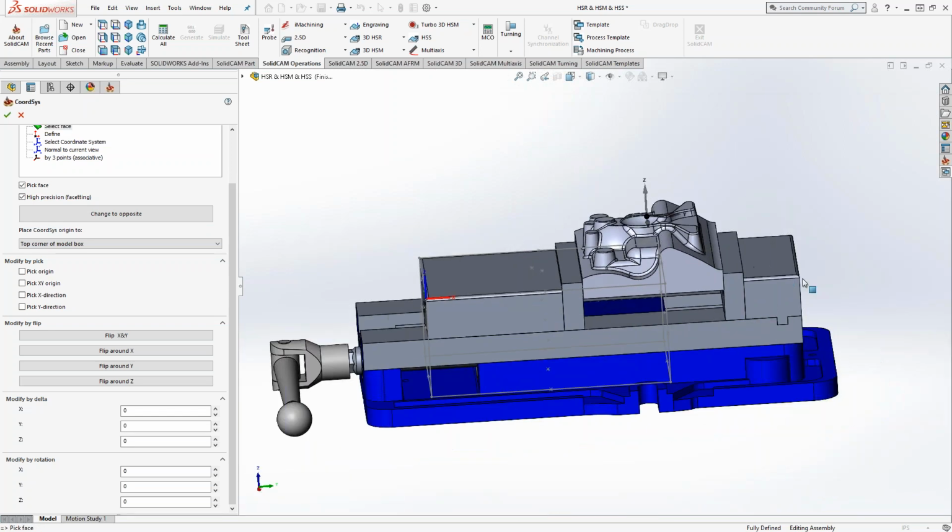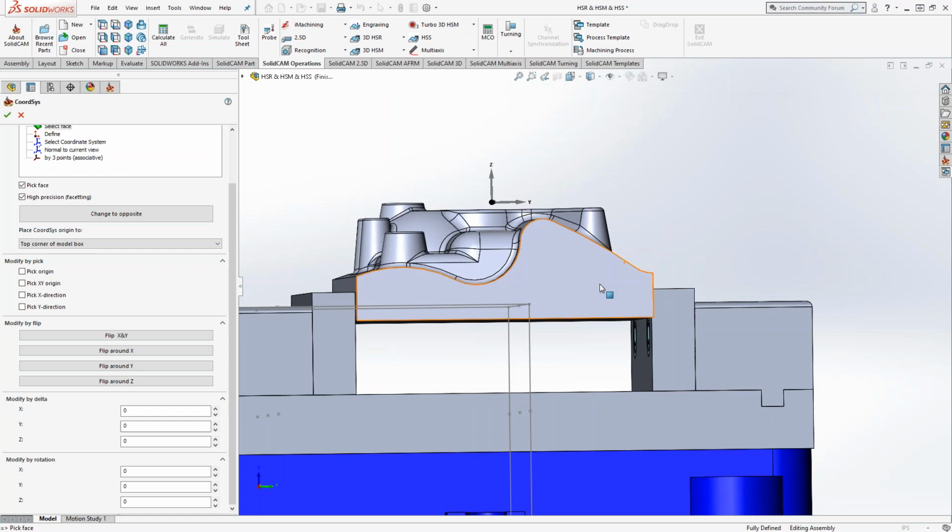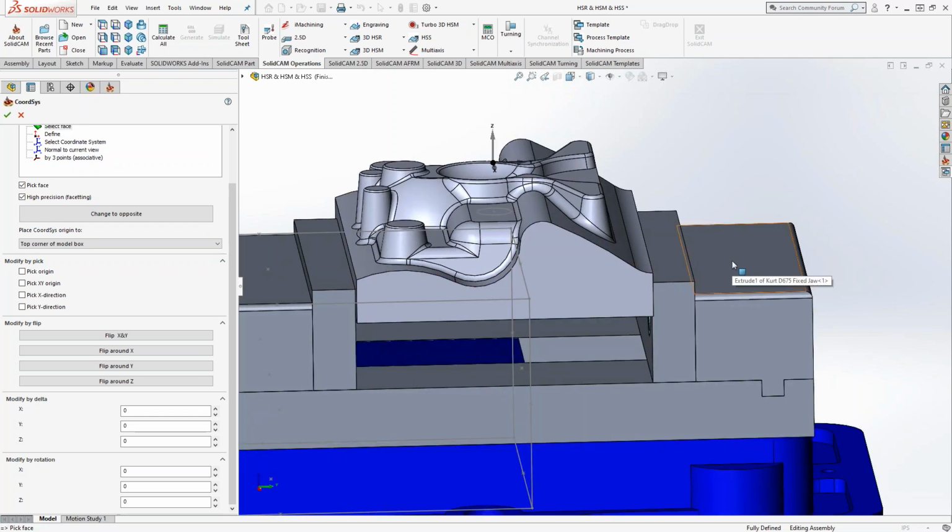If you know, for instance, let's say on a part like this, I only had this flat face here, but I don't know what angle that's at. I could measure it by actually measuring the edges. I can measure it maybe going from one face to another, or I could actually maybe make a sketch on this face, start a line that goes from that vertice up just freehand, and then using the SolidWorks sketch controls where you can do constraints, set that line to be perpendicular to this face or another face or some sort of other reference. And then you can actually just get your straight line. And then like Kevin said, with sketches, you can create your coordinate systems that way as well.